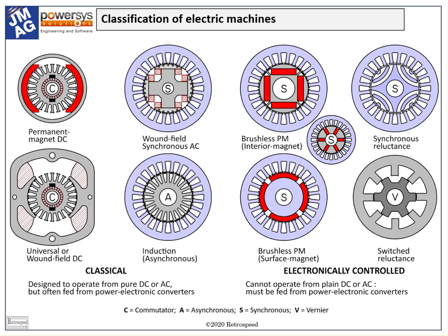Outside the family of AC drives, there are other viable types of machine which serve important functions today. On the left, for example, we have the commutator machines, DC at the top, and the universal AC machine at the bottom. The DC motor shown here has a stationary permanent magnet field, but in many important applications it uses ferrite magnets, which are less expensive and not subject to the same availability concerns as the high-energy rare earth magnets.